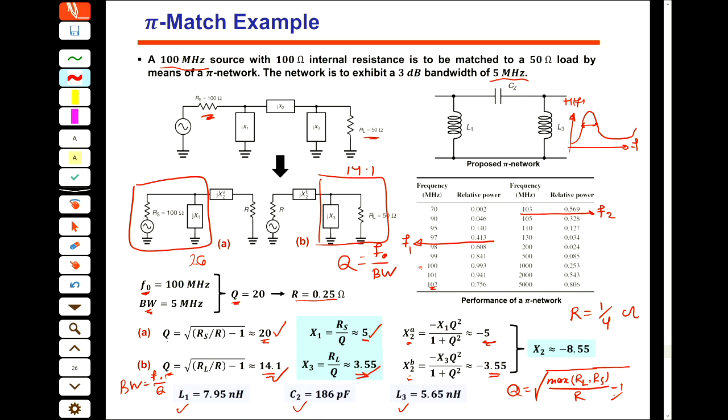Any question? So you can simulate this circuit. But if we simulate this circuit, what will happen in the LCL? Then you can simply simulate it in LTspice and see what the transfer function of the LCL is, and see why it's going high again.